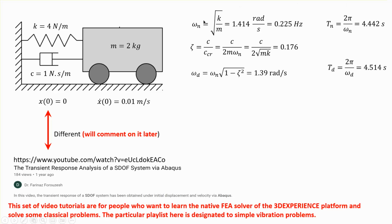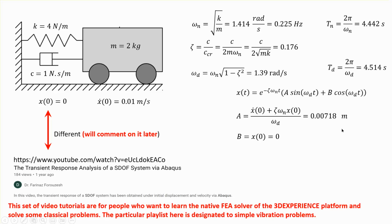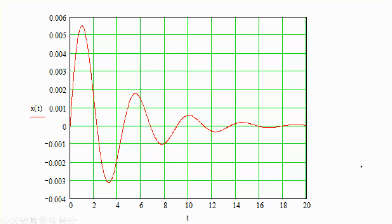Now these are basic formulas from a third year vibrations class. The natural frequency of the vibration, the damping ratio, and the damped frequency, they're all given here. And the solution subject to these two initial conditions is written as a one-liner right here, where the A and B are the constants, and assuming these conditions, they are equal to the values that are listed here. Okay. And in fact, when you run it, you're going to come across a damped harmonic problem that looks like that. Now remember, this is for 0 displacement.